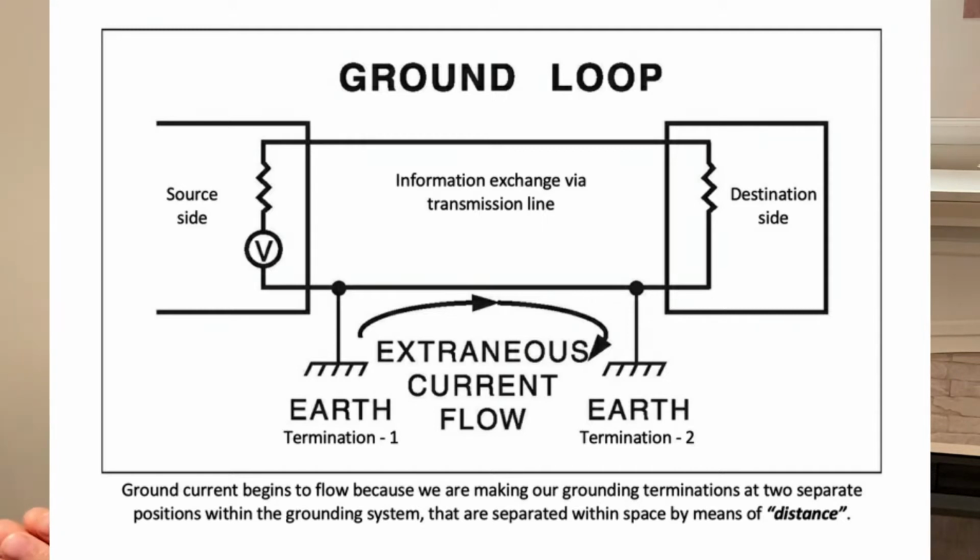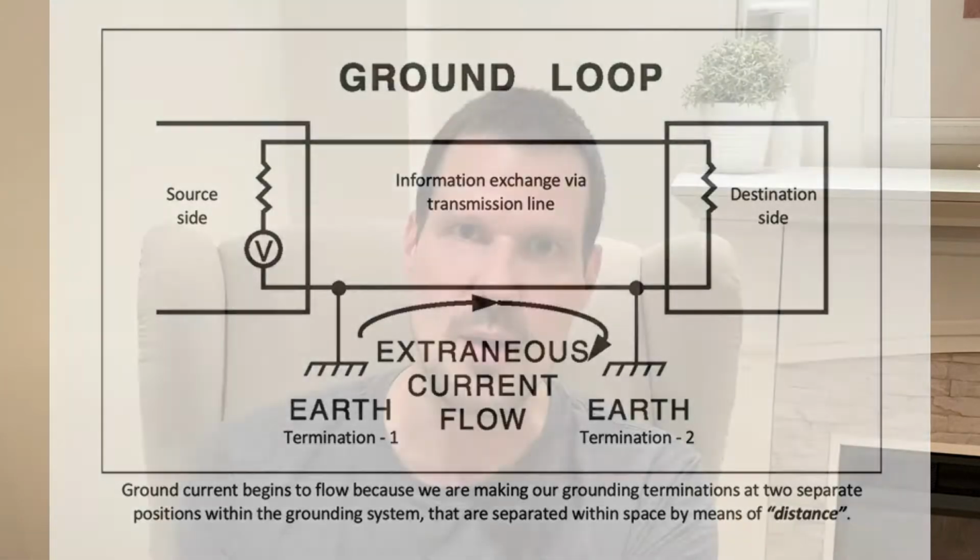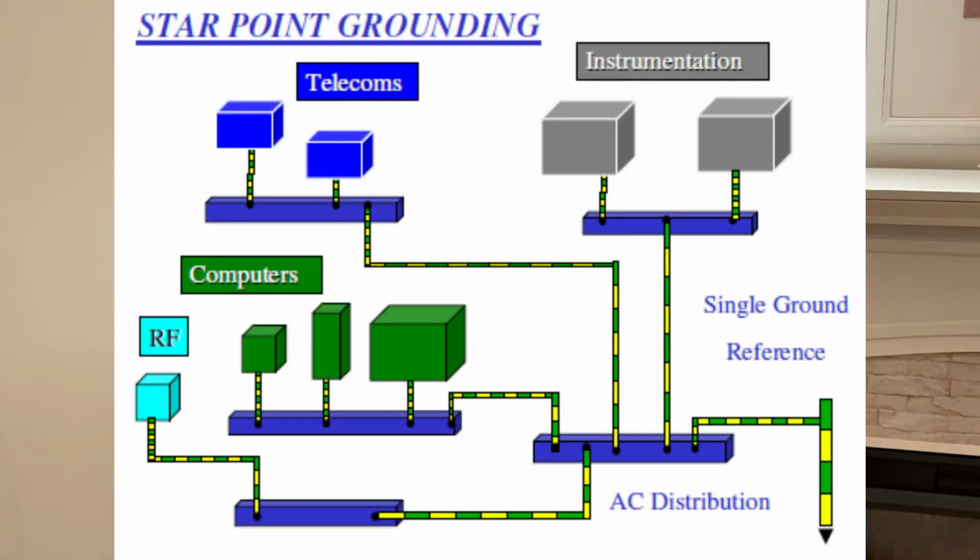And in the industrial automation industry where I came from, there were a lot of common grounding practices that we had to follow. A big one was that we had to make sure there was one central point where all the ground wires were connected, or terminated, is probably a better way to say. We actually call that a star grounding connection. If there are any electrical engineering people watching this, you'll know exactly what I mean. It was imperative that we maintain that.